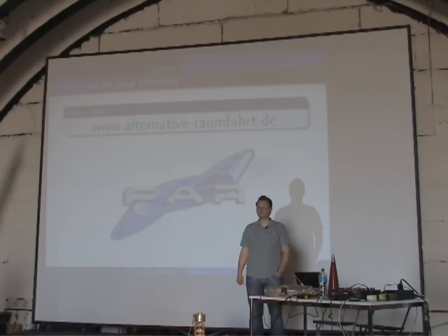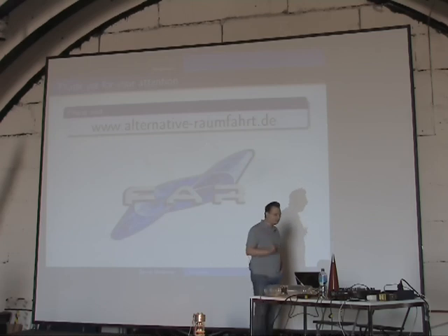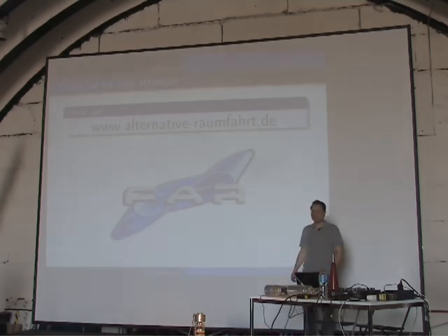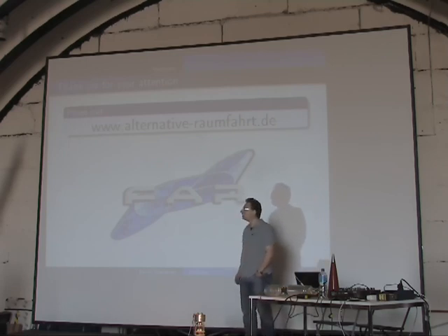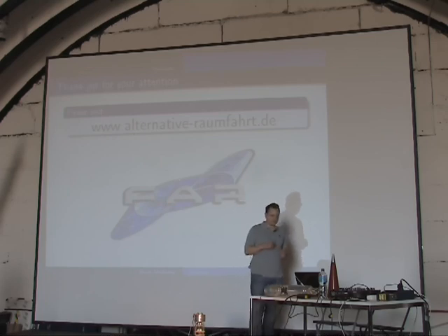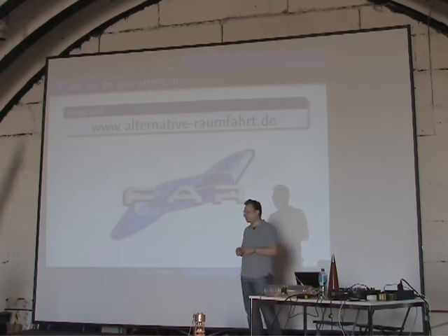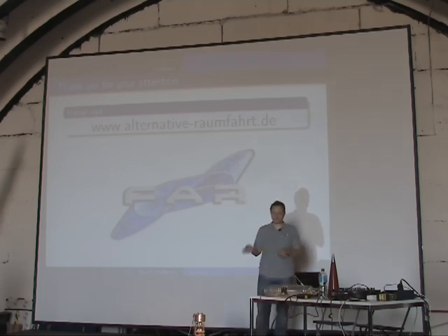Hello, do you see any option to get full redundancy to remove this voting machine, I think you called it? The problem is that, for example, attitude control is very important for rockets and other UAVs too. If you have an attitude control subsystem made of cold gas engines, and there are, let's say, 3 computers performing the same algorithm, and one of them wants to do something else than the other 2, then they will overvote it.